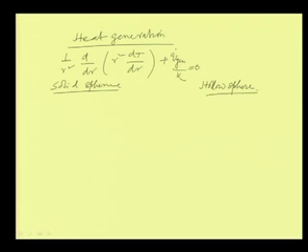Okay. And then for a solid sphere, we know that r square dT by dr is equal to minus q dot gen by 3 k into r cube plus C 1, and at r equal to 0, we know that dT by dr equal to 0.